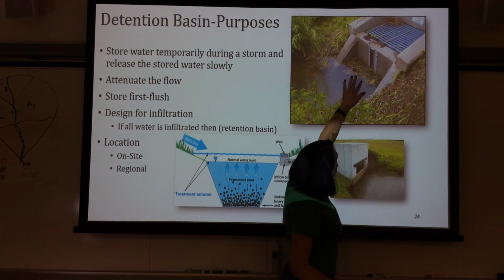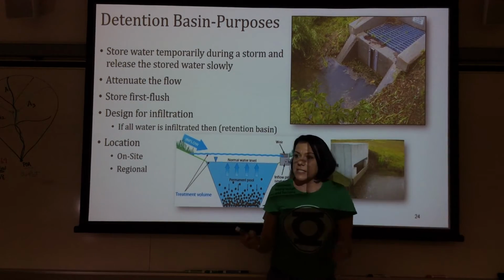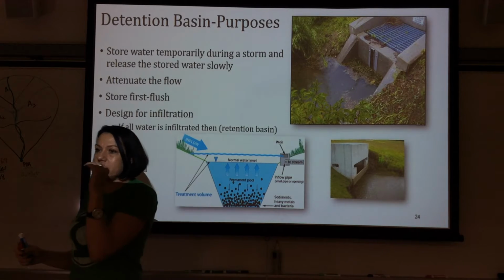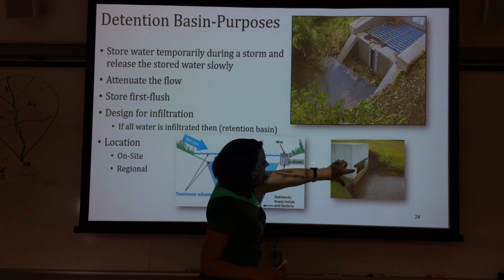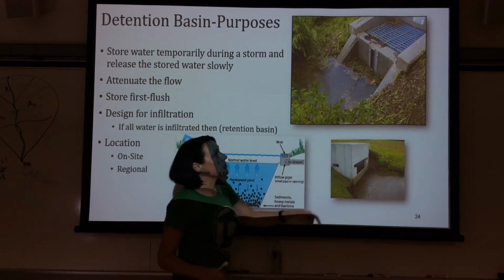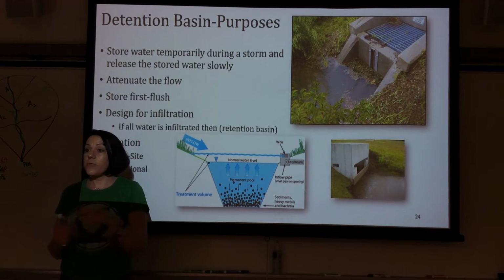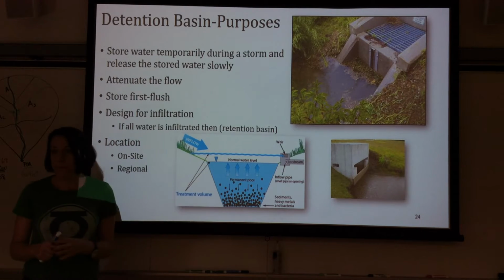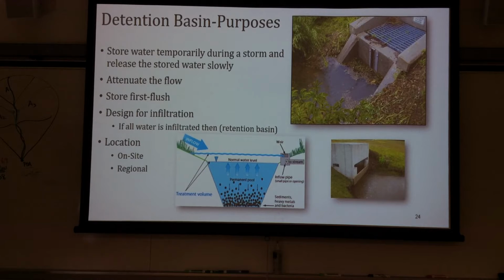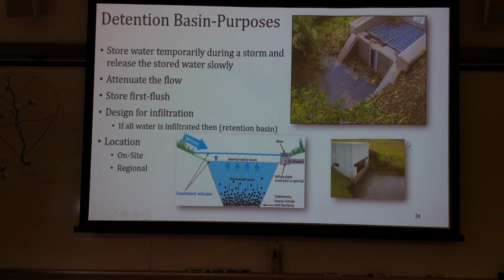See how water is stuck right here? Let's just say that bottom is the control. All right? So these objects here are weirs. Orifices are usually just circular or V-notch, and weirs are broad-crested or rectangular or something like that you're seeing here.